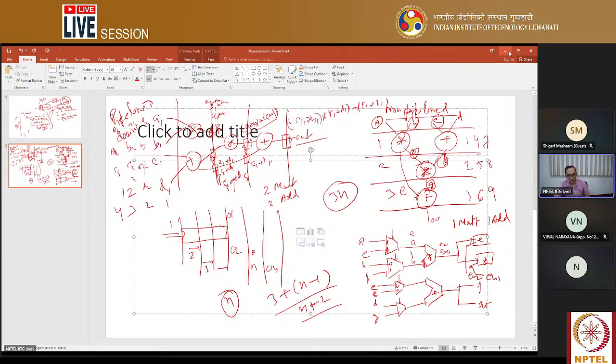All this schematic is actually available, right? If you install Xilinx ISE, it will give you the schematic diagram, so you can actually see the difference. The way I draw the diagram, you'll see a similar diagram when you create a pipeline and non-pipeline version of this design. You'll see this structure coming for non-pipeline. And you should understand the trade-off between these, right? Then only you'll be able to utilize this tool properly.